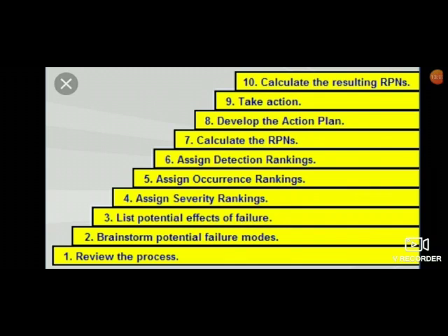Step number 7: establish the action plans which help to minimize the risk to the customers by using the RPN value. Recommended actions can only impact the detection or occurrence. Severity will remain the same until and unless the product or service or information is used for a different intent.